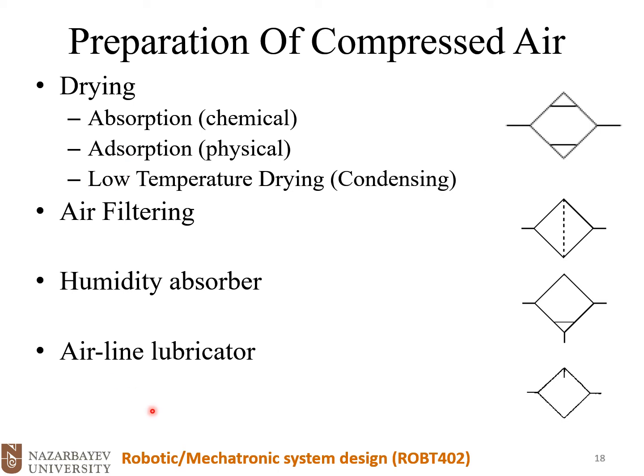And you could have an airline lubricator. Airline lubricators will add some oil to the air, and droplets of the oil will move by the flow of the air and will reach moving parts like pistons in cylinders, like spools in directional valves.